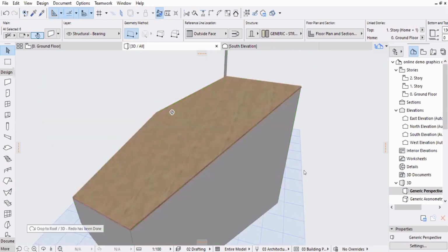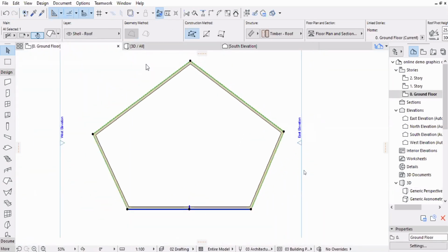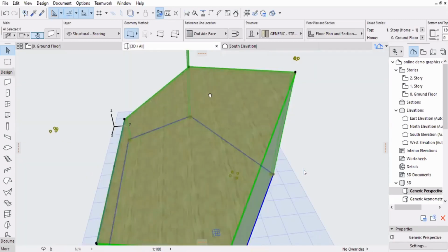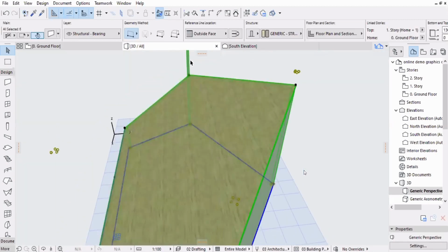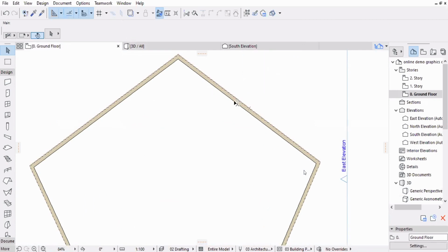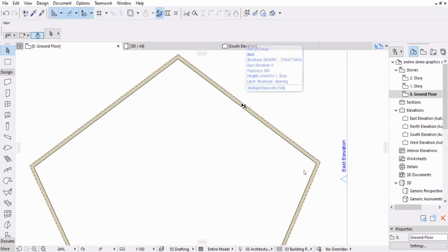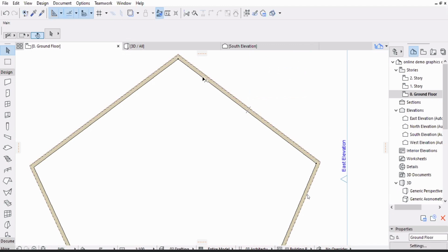Okay, what I'll try doing now is increase the overhang and see if that portion of the wall gets automatically cut. We have the roof selected already, and sometimes if you have things on the edge, you're not able to select. Say I'm trying to select the roof, but I'm not able to; I'm selecting the wall. So what is the way to toggle between these two geometries which are on the same edge? Very simple.